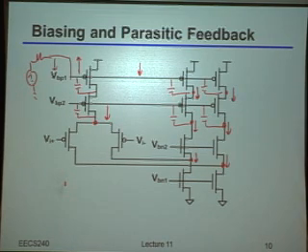That's right. You wouldn't have the correct current bias. It's actually, in some sense, even worse than that. If I take any sort of system and I make it unstable enough, what does it tend to do? Yeah, it oscillates. So in this particular context, it would mean that the common mode would oscillate, for example, between 0 and VDD. Maybe not exactly that, but close. And as should hopefully be clear, if your common mode was oscillating between 0 and VDD, differential mode is unlikely to do anything particularly useful, because the whole thing is just not biased properly.